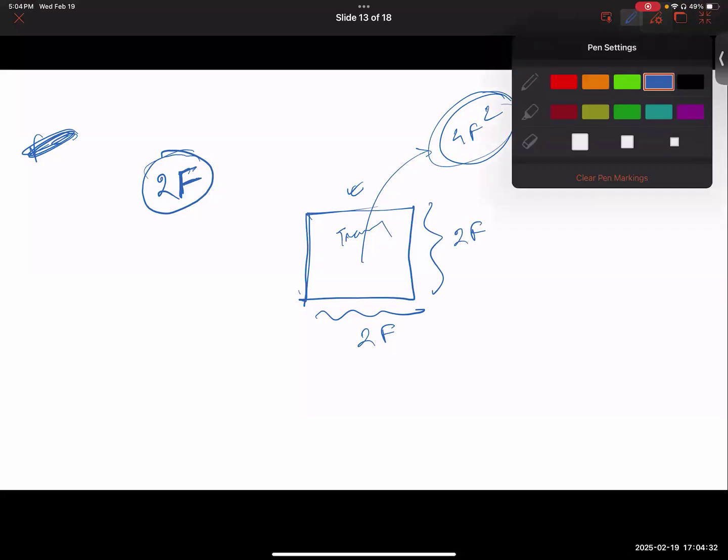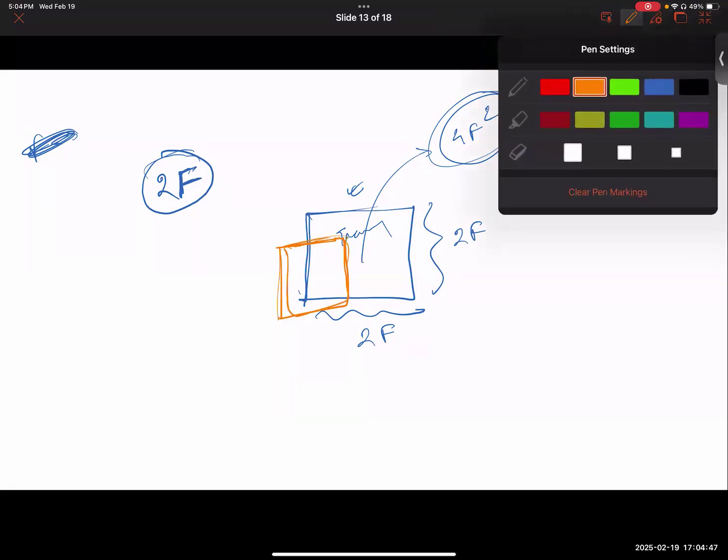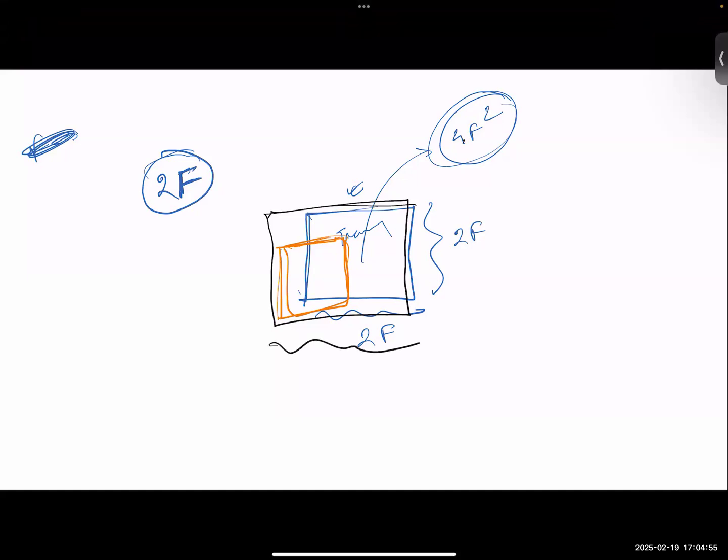When you try to scale up your capacitor, you obviously want to make a bigger capacitor to store more charge. The capacitor could take more area, and there could be an offset in terms of area. If there is an offset, what is the total area? The total area would be something like this, including the capacitor and the transistor. So instead of 4F square, you get more. The area eventually could become 6F square or 8F square or more than that, depending on how much offset you have in the capacitor.